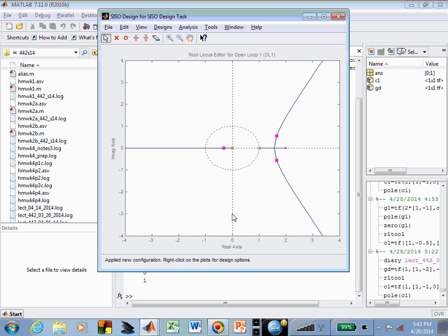Well, the 1 is, but you have 2 that are not. Because of the poles at 1 and 2, those 2 branches coming together and going off to 60 plus and minus 60, they're not going to go into the unit circle. So now let's go up and fetch some of these poles and zeros, and the zeros, luckily, MATLAB uses open circles like we've agreed to do. And now you can simply go down here and put 1 in.